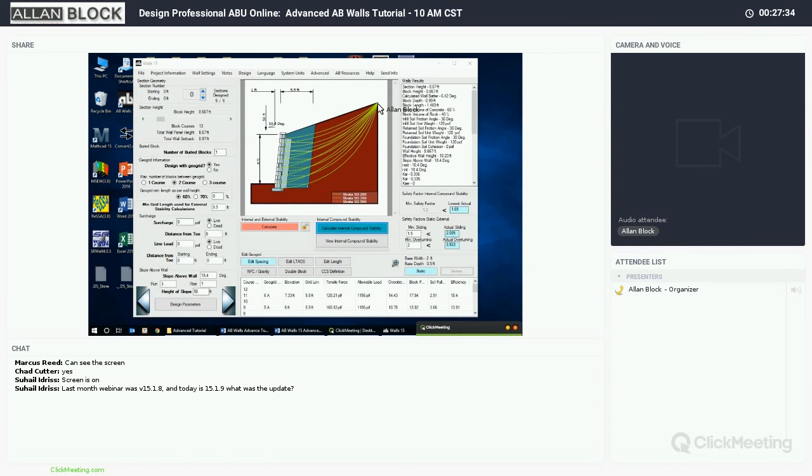Notice now that same 8-foot high wall in clay soils with that slope above, I need 9.5 foot of grid. So there are many instances that if you raise the height of the wall and reduce the slope above, you can in fact build a better structure and actually have less grid requirements too, because right now you're relying on this mass to hold up this entire hillside.